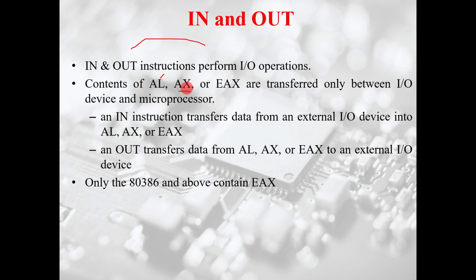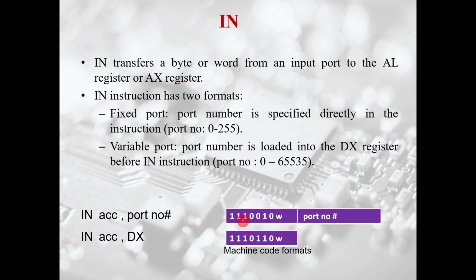No, data cannot be transferred from the ports to any register other than AL and AX. EAX is for the 80386. Similarly for the out instruction. We'll see some examples, and it will be clear. The in instruction transfers a byte or a word into the AL or AX register.